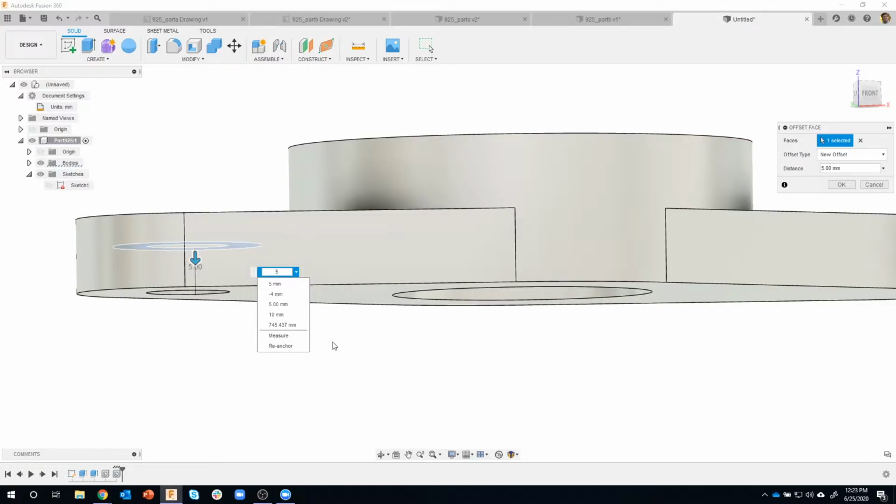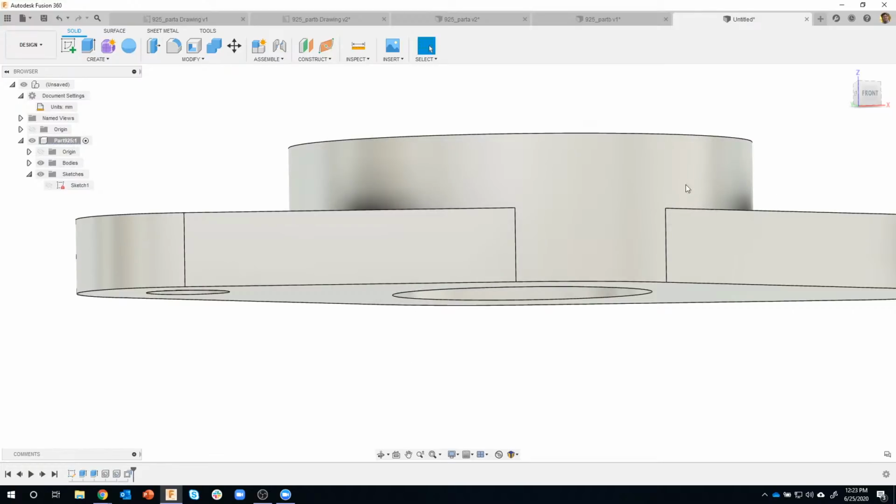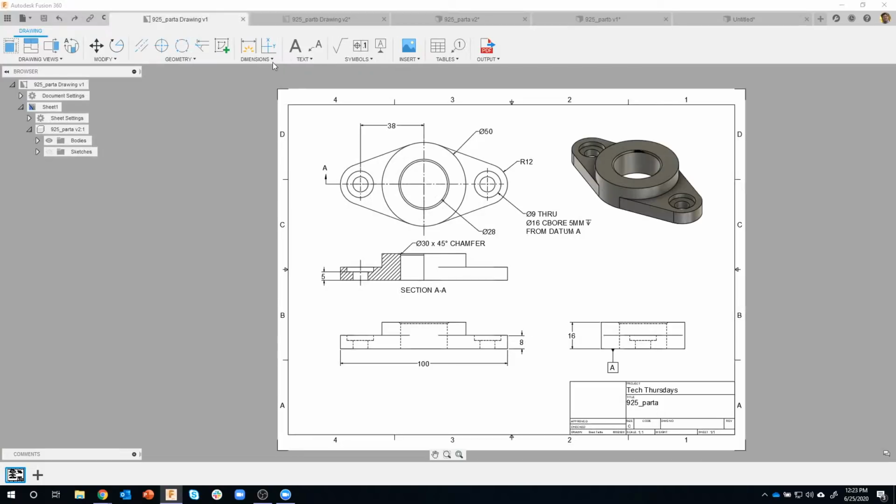command. It's extremely powerful. And the only reason I'm showing you this is because you don't know how you're going to get the drawing. Maybe they said the counterbore is 2.5 millimeters deep. Okay, that's great. But in this case, the drawing was saying there needs to be 5 millimeters of thickness here before that counterbore.